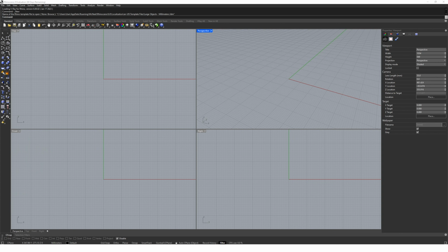If we want to create a box, we can just type box, and if we want to draw a curve, we can type curve, and so on and so forth. The command line will then respond with options on what to do next. So when using Rhino, it's critical to always watch the command line and respond to prompts.